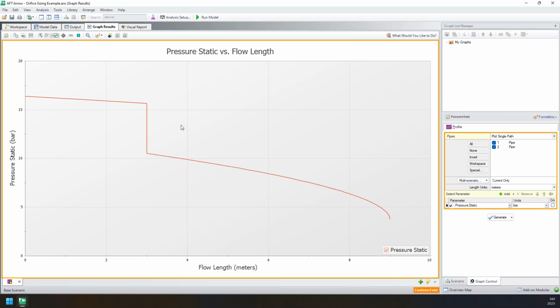So if we recombine all of our windows together, here in graph results, we see the gradual decrease in pressure as we get flow through the piping and we have those frictional losses. We see the very dramatic decrease in pressure as we go through the control valve, which is really throttling our system, again creating a high pressure loss to restrict our flow. And then here we see, again, that increase in pressure loss due to friction, and we see it starts to increase more and more over time. So that's kind of an odd phenomenon, not something you would expect in incompressible flow.